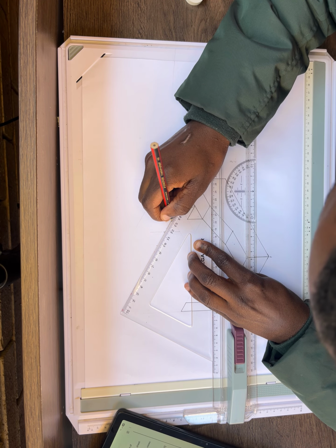In this box is where we are going to put the what? Our half a circle. You know that this has got an angle that is greater than 90, and also this side has got an angle that is greater than 90. To get an arc here, you must put your compass here and then make the arc. So which means now I'm going to put my compass here and then make the arc.